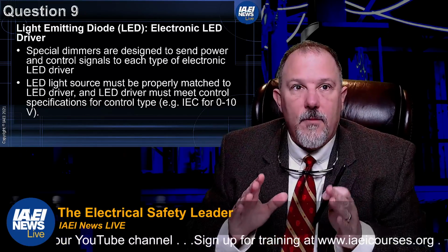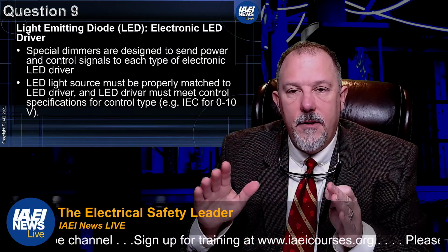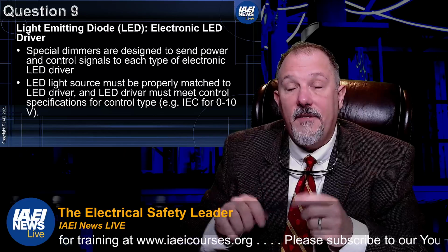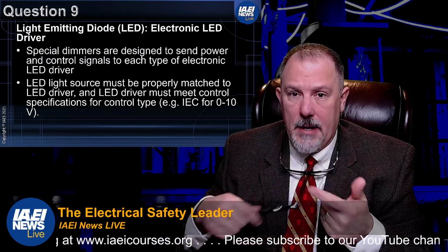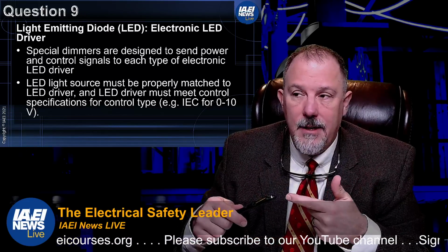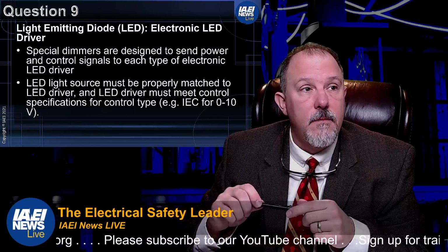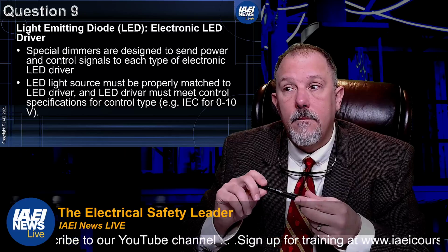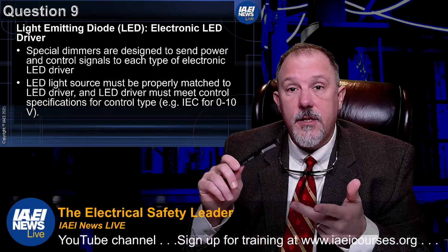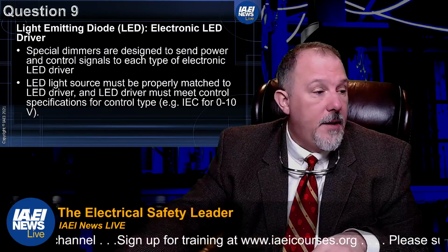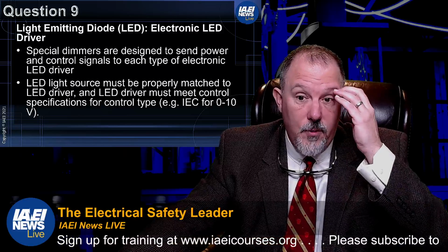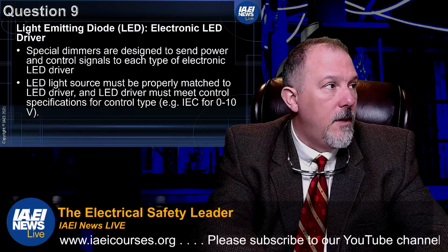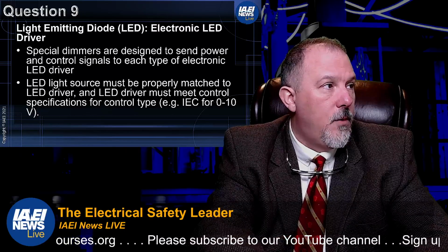So, depending upon the technology that's on that branch circuit, I have to think about my overcurrent protective device compatibility and listing, and I do have to think about the listing and compatibility of my dimmer switches, occupancy control switches that are listed to be used with those applications.